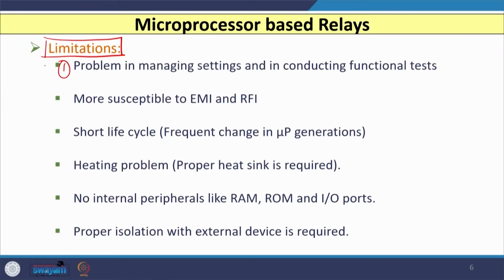So, the first limitation of this relay is the problem in managing the settings and conducting the functional test. We know that this relay has a large number of settings. So, managing the settings is itself a big issue. Of course, for managing the settings, certain setting management software is provided by the manufacturer. However, still the person who is involved in the setting or in the functional testing of the relays is very expert and knows all the things related to the settings of the relays.